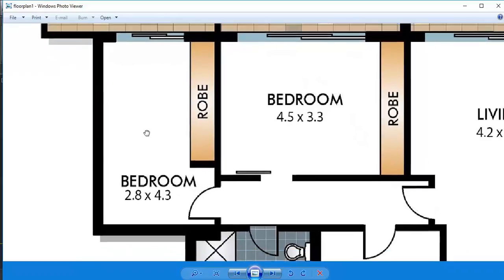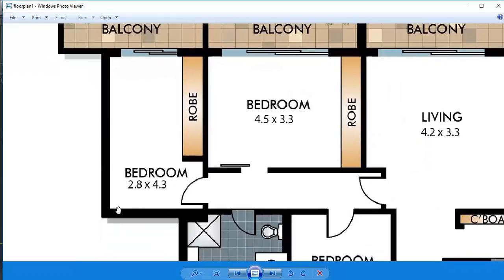Fair enough. And you'll find older buildings from a certain era, that period after the war up until the 70s, 80s, when they did those really small rooms. Mostly post-war, but it did start with the beginnings of modernism, so you'll see it sometimes with the pre-war buildings, but usually they're bigger. Nowadays 3 metres would be the minimum dimension you'd find in a bedroom in either direction for a new building, but from this area you'll find sometimes they do have those small ones.